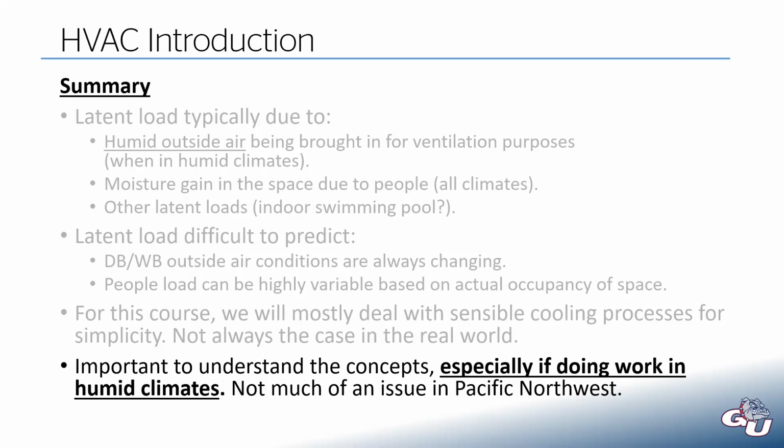In the Pacific Northwest, we've got it real easy here. We have pretty dry air, so our latent load, at least from our outside air, is pretty easy to deal with. We still have some other things we have to deal with, like moisture gain due to a bunch of people loading up in a space. But just know latent load is a big deal in some climates.